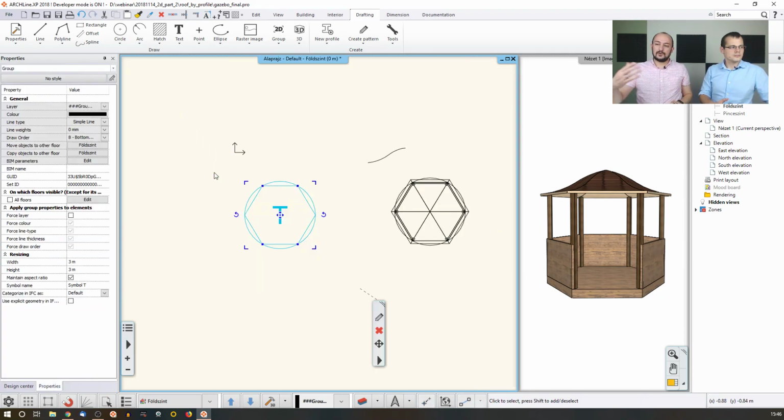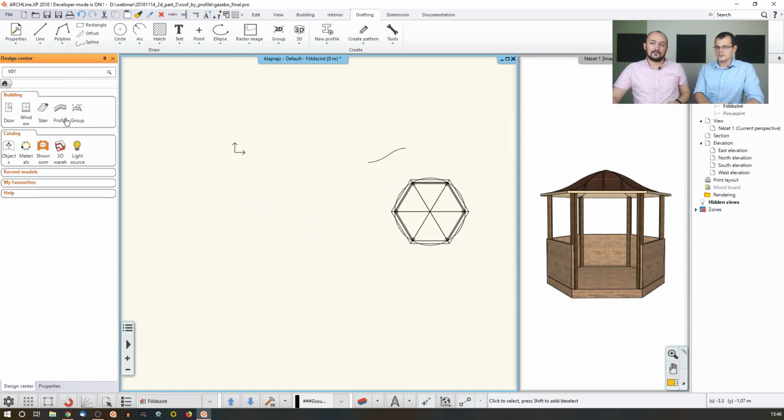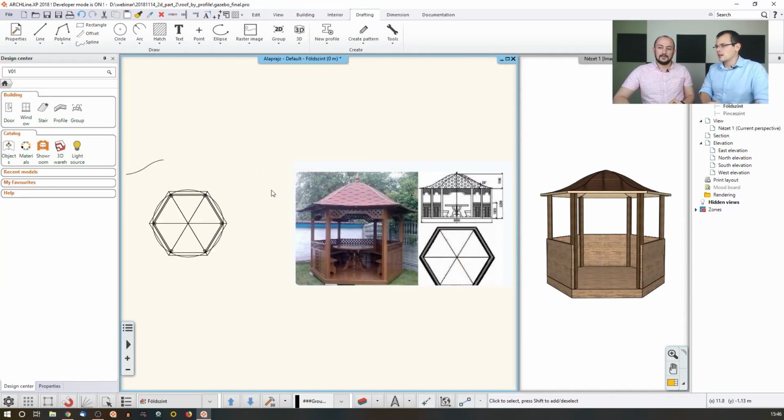Remember that whatever you create, its default size will be the original size how you create it. So that's why when I refer to the groups as title boxes, for example, when you would like to define or create your own title box, design it in the real world size, like the paper size. If you know that you have a title box for an A4 paper, design it in that size, and then you don't have to continuously reshape and resize it for different purposes. Yeah, so draw everything in one-to-one. Just like we did with the walls, doors and the roof panels, we always work in one-to-one.